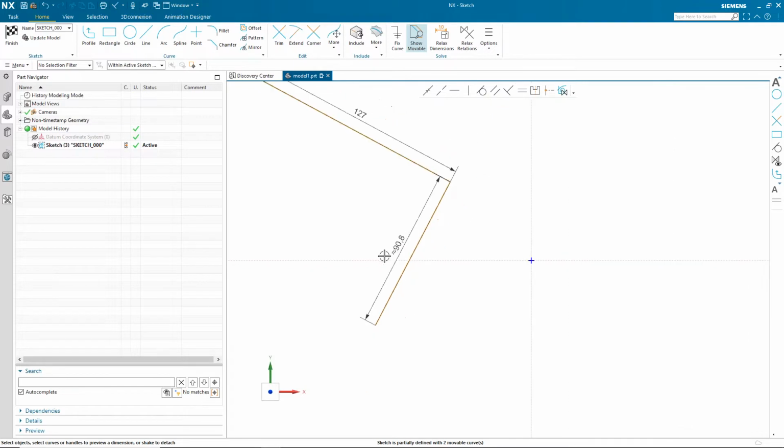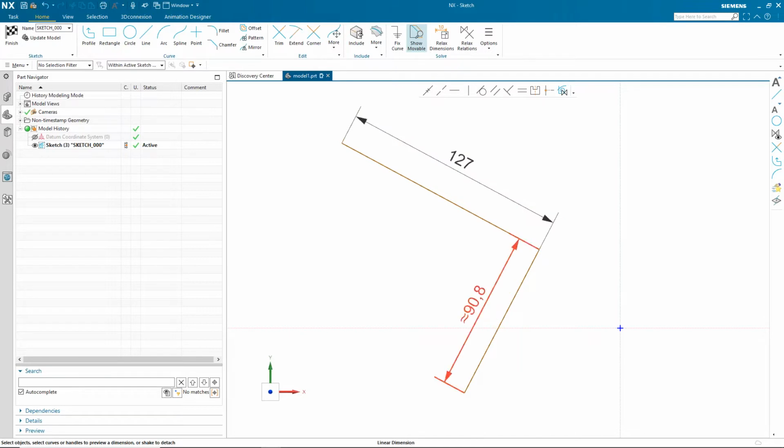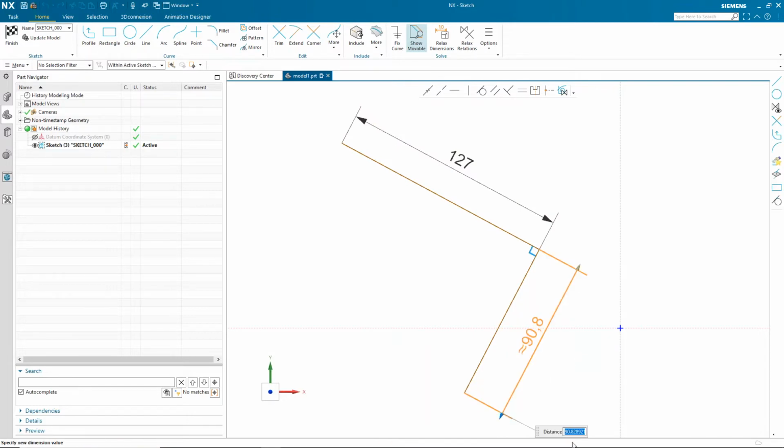Another thing to notice with the new sketch, let's do this, is if I hit my control key and my up or down arrows like I do in Microsoft products, I can make my numbers bigger, and I'll make them bigger for you guys to be able to see. If you ever come across a dimension as you add it and it has an approximate sign, all that's telling you is it's not displaying all the digits it has on the screen. Like the first one, I just drew to 127 when I dragged it around. This one's about 90.8. If I double click on it, you'll see the number here. It's 90.8289621. So it's about 90.8. So just so you know that too. That gives you an idea. If you want to maybe round that one off to 90, I can just put it in and go 90.